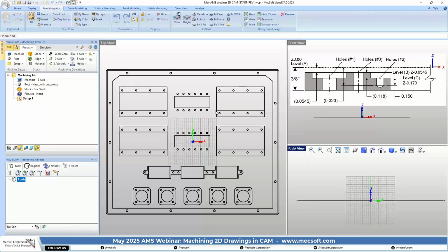For 5-axis, if you're going to do continuous 5-axis or surface milling, you do need to have a surface, obviously, or you can do it with a mesh. If you're doing a continuous toolpath operation in 5-axis, you have 2 different types of geometry types. You have drive regions and check regions.